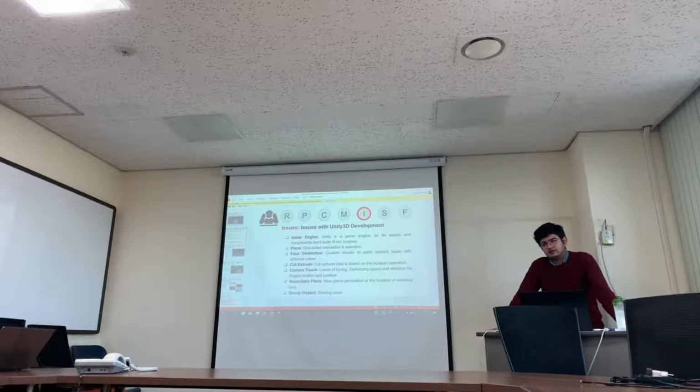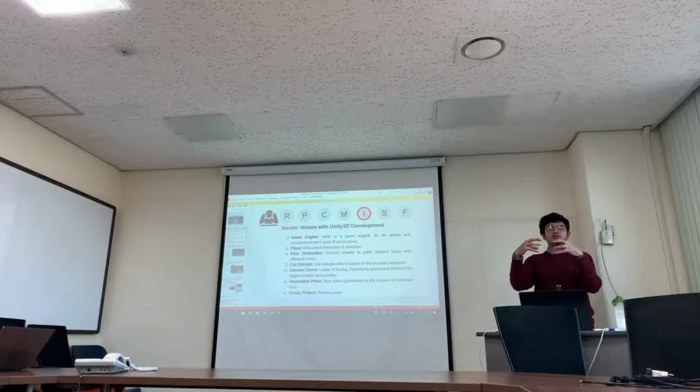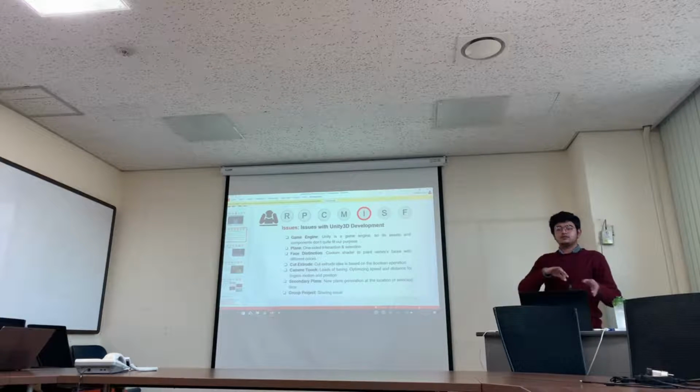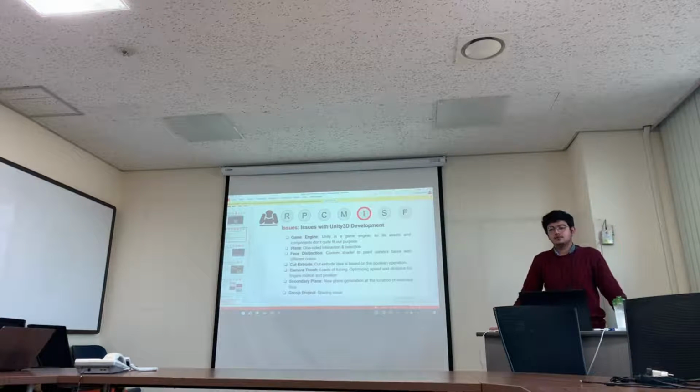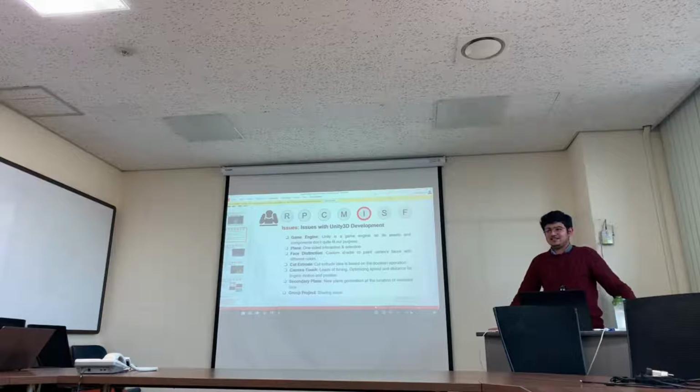How do you determine the direction of the extrusion if you select a face? The material addition, which side will it be? I mean the direction. If you select the face, it could go not along the normal, but it can go there or there. So there is a minus in the keyboard, like plus or minus. And what about if you select one of the faces of the circle and the normal is not parallel to any of the axes? You can try that. Basically, a circle, because it has many sides, has many small planes, and you can draw on the small plane.